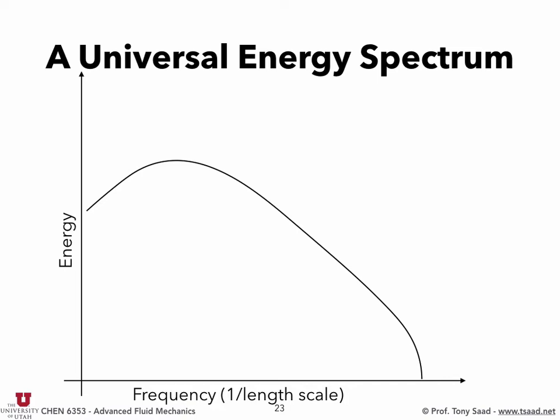So this explains the spectra we were talking about with the turbulence generator the other day. Anyway, that's a unique signature of turbulence. So I'll give you an example of how this is useful. In simulation, sometimes you want to introduce some randomness. In an inflow boundary condition, for example, you want the inflow to fluctuate, just to trigger turbulence per se. And one would go and put in a random number generator. You have a parabolic velocity profile, and add a random number generator at each point of the inlet.